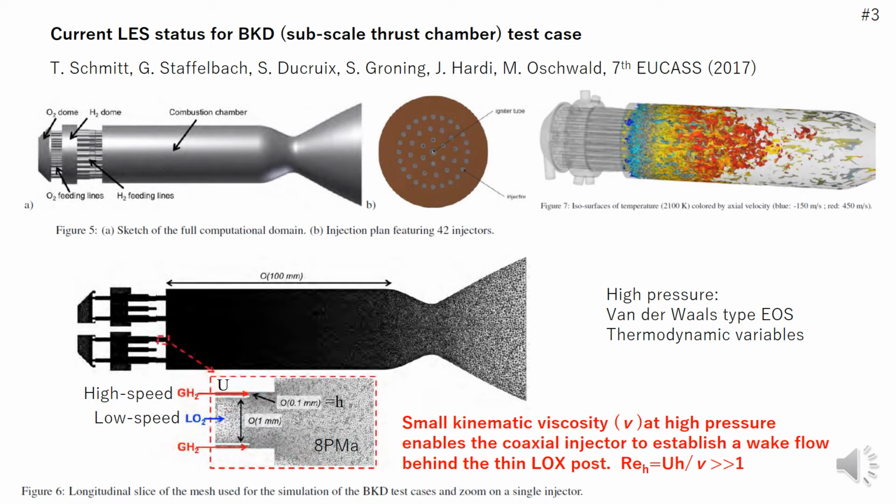Now, there are LESs which simulate the whole combustion system. Small kinematic viscosity at high pressure enables the coaxial injector elements to establish wake flows behind the thin LOX posts. Such a situation is similar to that of diesel engines and gas turbines.